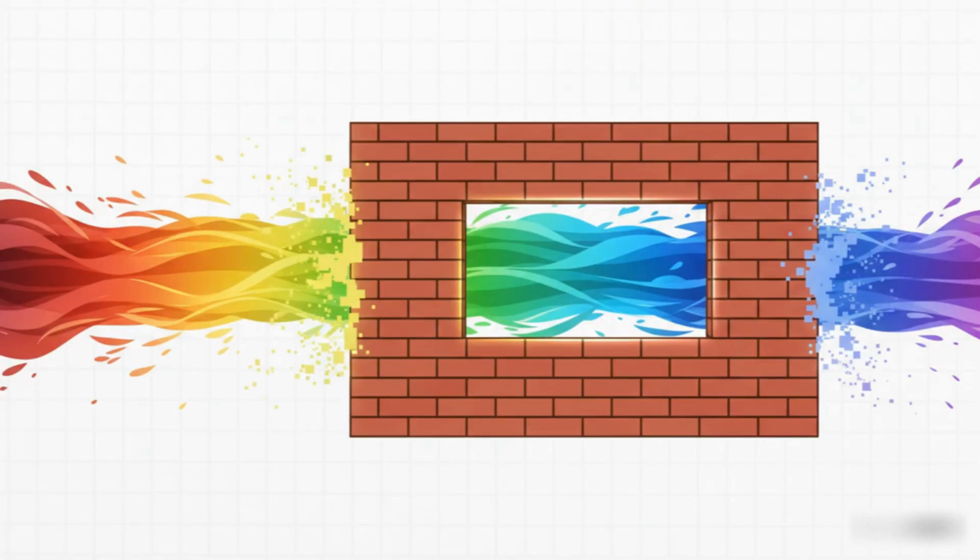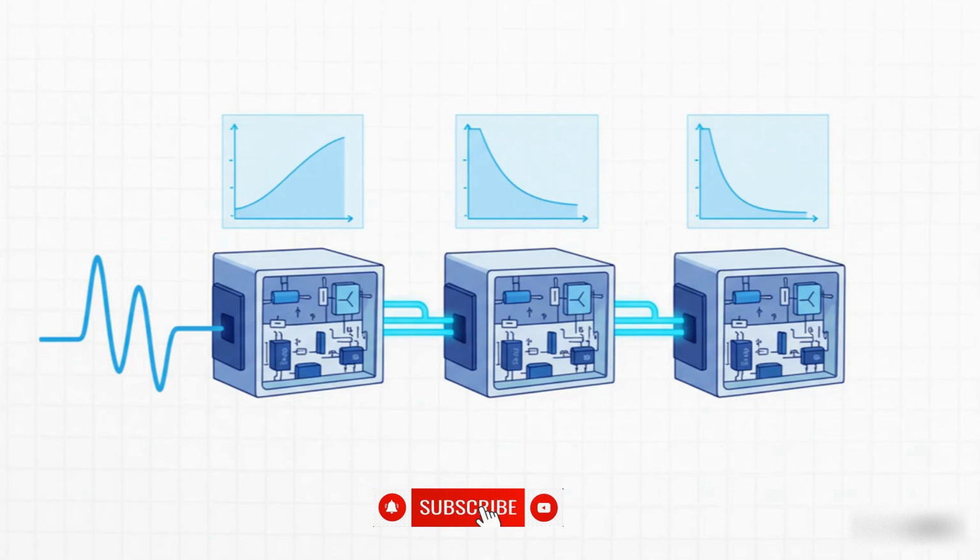In a perfect world, a filter would act like a literal brick wall. It would let every frequency we want pass through completely unharmed, and then, bam, it would instantly block every single frequency we don't want. Now, of course, a true brick wall filter is impossible, but how do we get as close as we can to that idea? The solution is actually surprisingly simple. We just increase the filter's order.